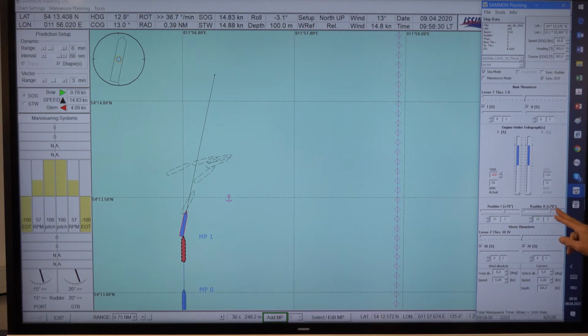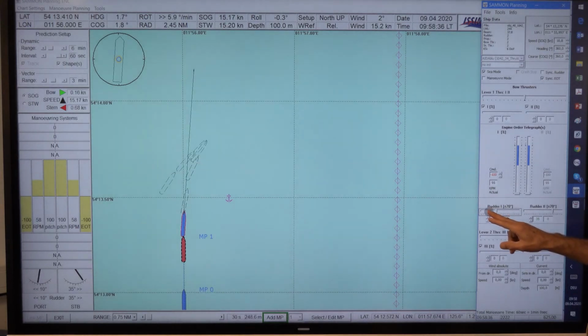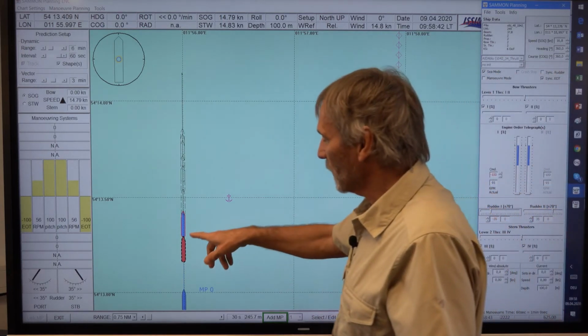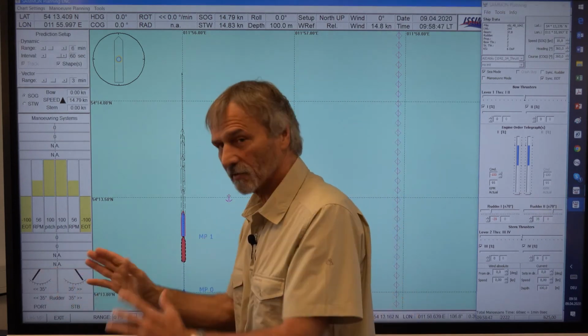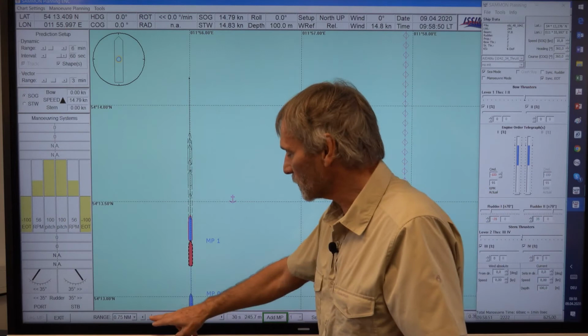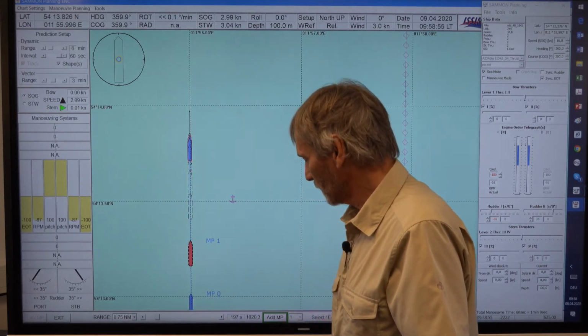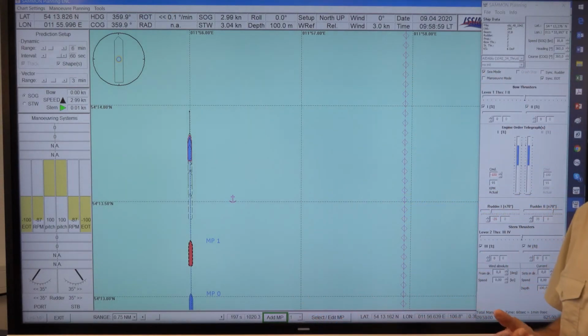So this rudder is to 35 degrees and this rudder is going to minus 35, that means to 35 degrees to port side. So what we see is the ship is going straight because the rudders are spread outside, and the stopping distance, only to measure the stopping distance, is now here 1000. So we are 100 meters shorter.